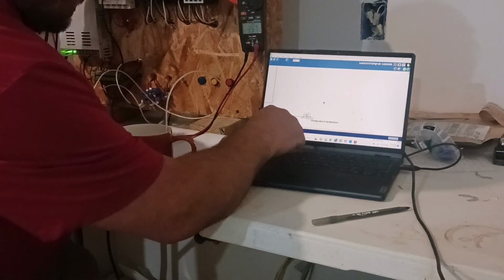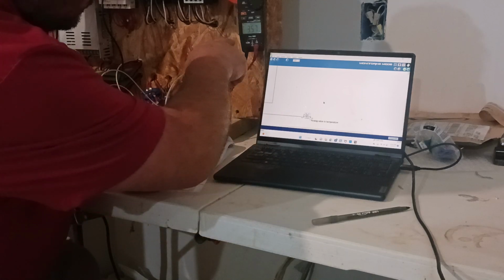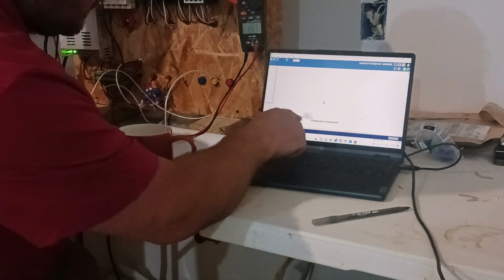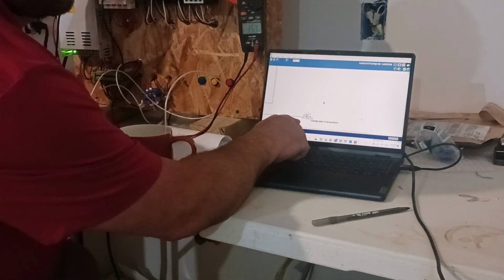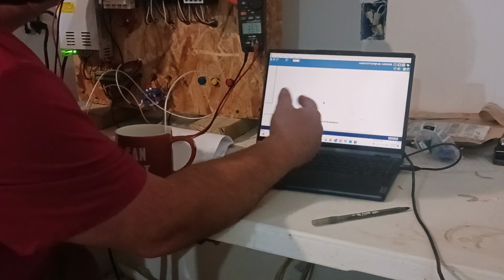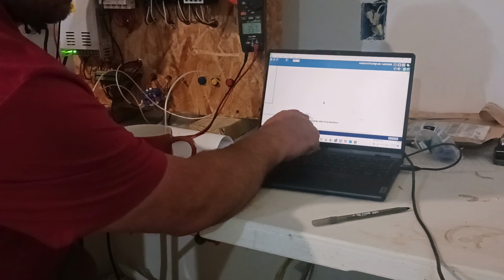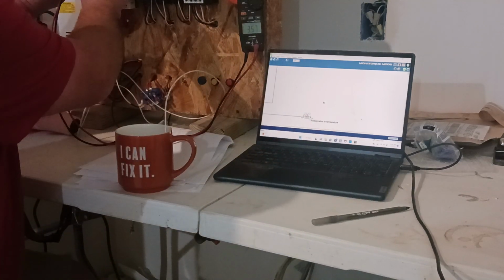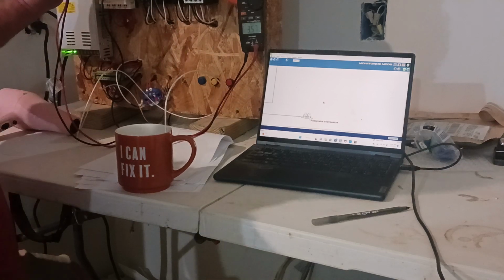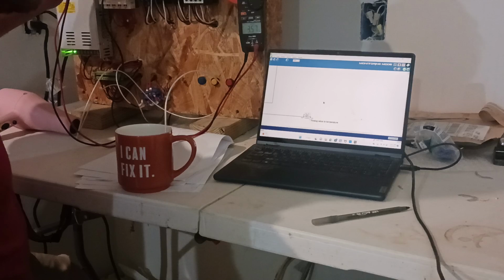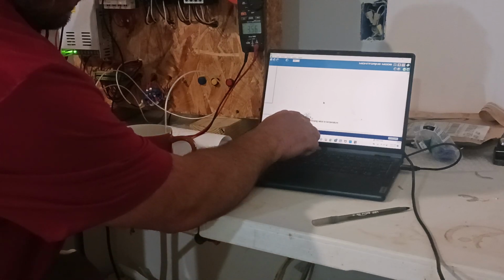3.57 is the actual voltage. Basically, you notice my resolution isn't that great, because you'll notice it flips. Every one of these numbers actually changes it by 12. So I can only get the degrees to within about 12 degrees. It's terrible resolution. But anyways, you'll notice I'm down to about 30 degrees.